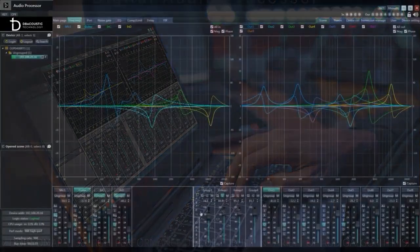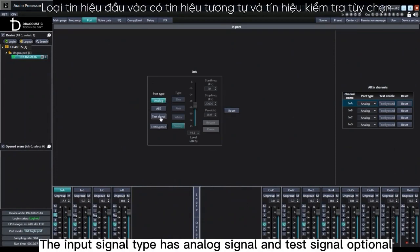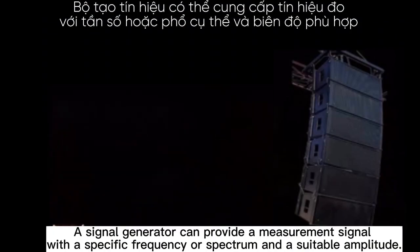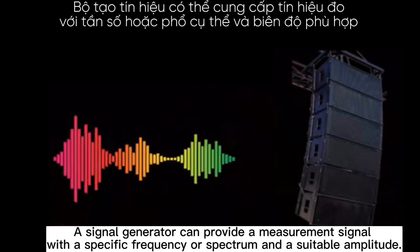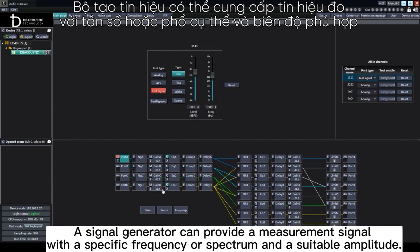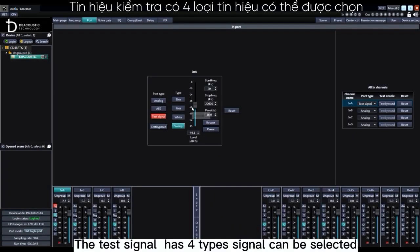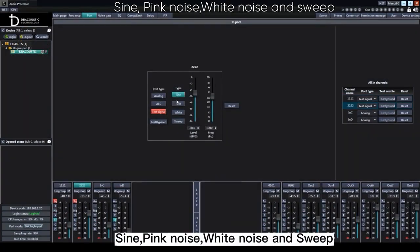Port setting. This is the port setting page. There are input port setting and output port setting. The input signal type has analog signal and test signal optional. A signal generator can provide a measurement signal with a specific frequency or spectrum and a suitable amplitude. Before enabling the test signal, complete the routing settings to complete the signal test. The test signal has 4 types. Signal can be selected: sine, pink noise, white noise, and sweep.